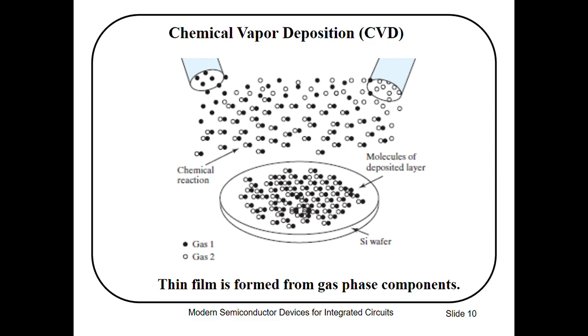Sputtering is the chief method of depositing aluminium and other metals. Sputtering is sometimes called the method of physical vapor deposition (PVD). While sputtering is a relatively simple and satisfactory way of depositing thin films over flat surfaces, it is directional and cannot deposit uniform films on vertical walls of holes or steps in surface topography. This is called the step coverage problem.